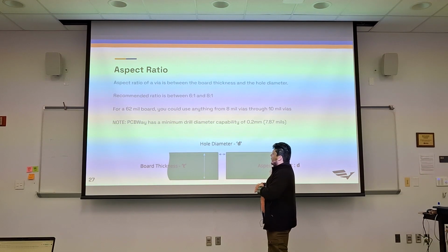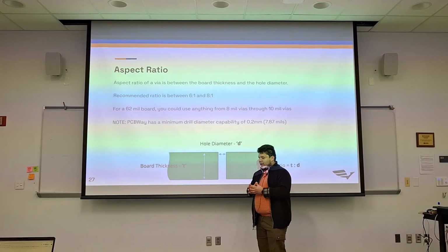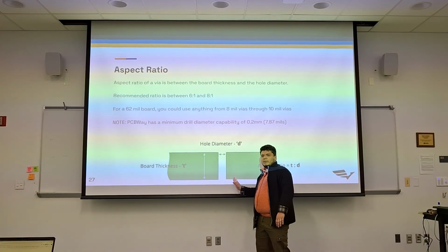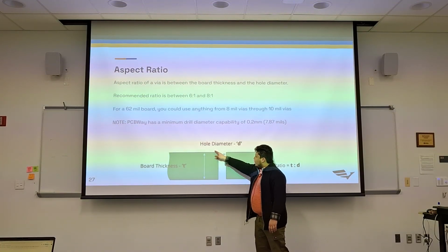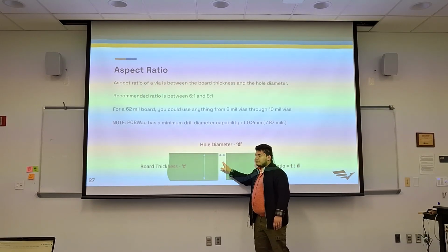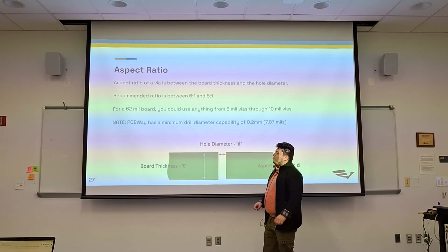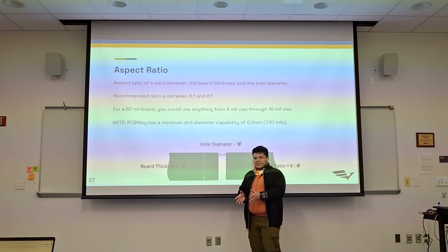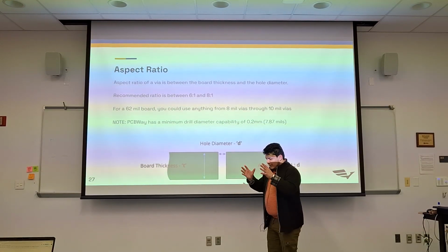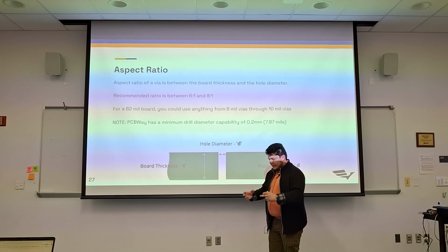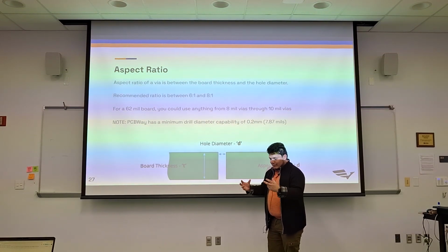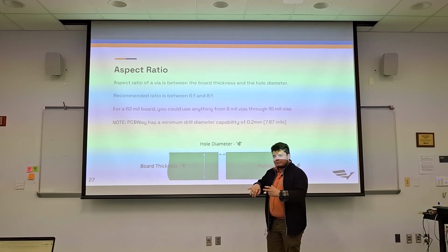So we're removing material. But also with vias, since they make the electrical connection, these holes have to be plated, right, internally, so that electrons can flow through the via. And so plating is done using chemical deposition, right? You immerse the PC board into a solution and electrically deposit or etch and plate this copper, right?